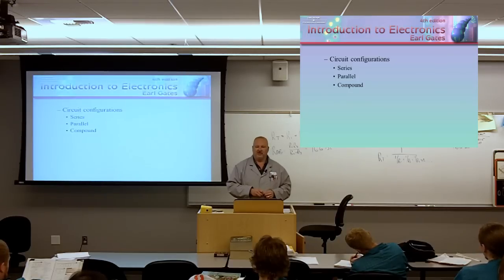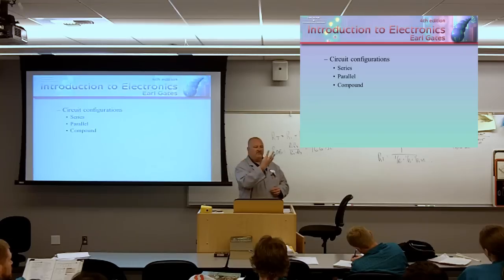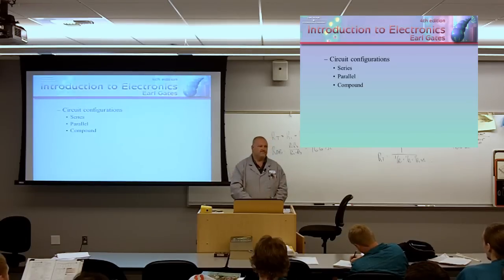Any questions out of this chapter? You add up the resistors or you just divide them out? In parallel, you got to divide it out. So if I've got 4 100 ohm resistors, it's 100 ohms, 100 ohms, 100 ohms, 100 ohms. 100 divided by how many resistors? 4. 100 divided by 4 equals 25. I should have approximately 25 ohms across that circuit.